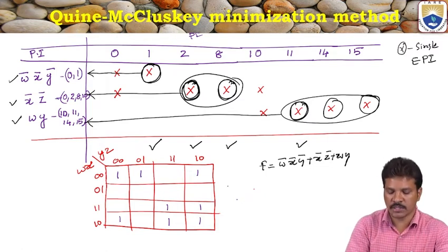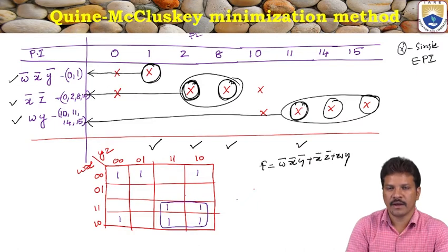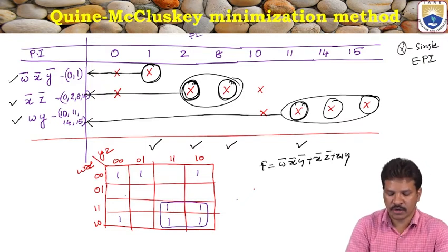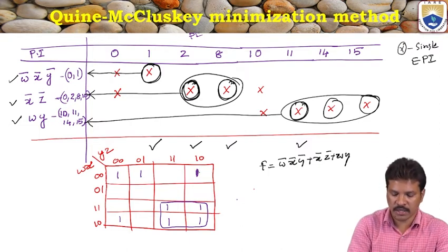Yes. There are 2 possibilities for 4 ones. First we will check this one. So this is one prime implicant group. Adjacent ones make this quad. And then, in order to cover the remaining ones, the first priority is 16, there is no 16. The second priority is 8 ones, there are no 8 ones. And the third priority is 4 ones. Is there an adjacent 4 ones to cover this one? Yes, we can take that one, like this, the 4 ones adjacent.